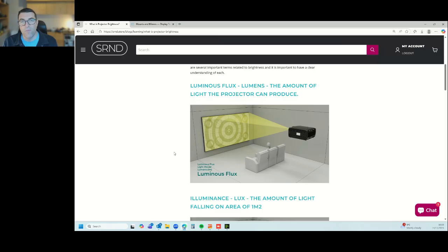If you're maybe doing a media room though that's got lighter coloured walls and maybe a little lamp or something like that, you will probably need to think about a much higher level of brightness. Because remember, a projection system works by reflecting light back off a screen. The blackest black that you get on a projector screen is determined by how much ambient light there is. You can't make it darker than the lowest level of ambient light. So you need to have more than that ambient light to get any sort of detail in the image.